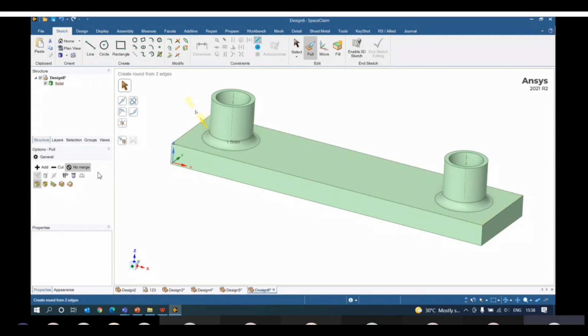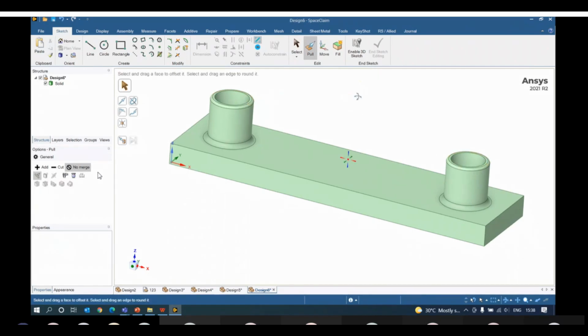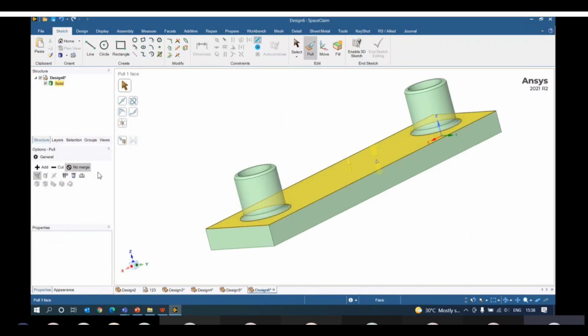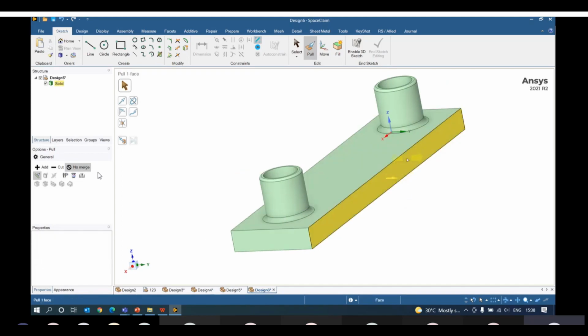So towards the arrow direction, I'm trying to add and say 1. Okay, same thing to both the edges. I'll try to give, let's say 0.5. Okay, and here this is done. And in case I want to create some wall here, I don't have to take a plane or something, directly I can select this edge and go with edge, like extrude edge, so that I'll try to get an edge here.